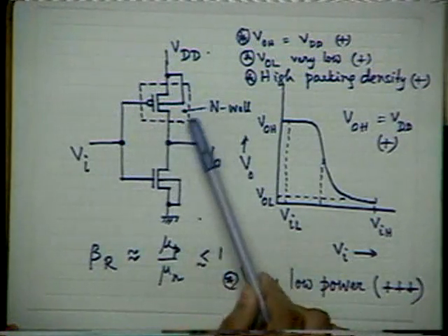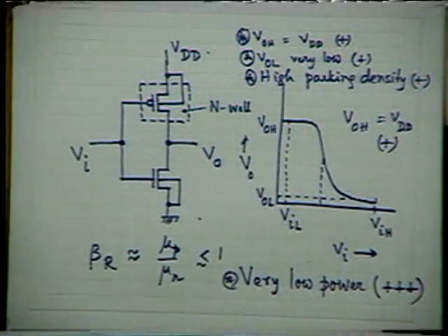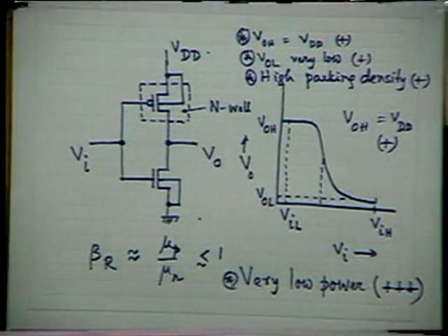And in this N well, there is a parasitic transistor here. And there will be charge storage, which ultimately gives rise to more delay. This is an additional problem. More capacitances involved, more parasitic capacitances. So many junctions are there. And naturally, it adds to the delay. It increases the delay. But then people are saying that CMOS can reach 100 picosecond, 50 picosecond. Then what is it that people have done? Simply by miniaturization.